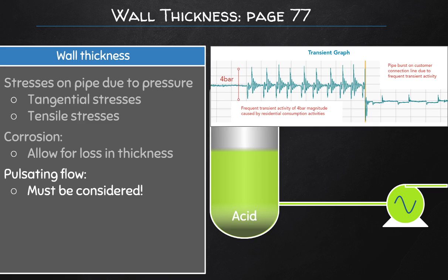to just assume this. So this is considered to be quite a considerable variance, and at times we often don't take this into account. It's very important that you take this into account and try to control for it. There are things that you can do to dampen out these effects, of course, but also just design the pipe so that it can withstand the highest foreseen pressure that is induced by the pump. So the results may be disastrous if you don't, and you must be aware of these types of hidden dangers.